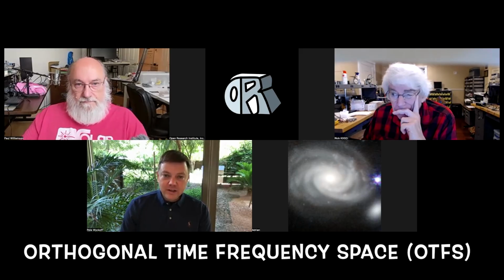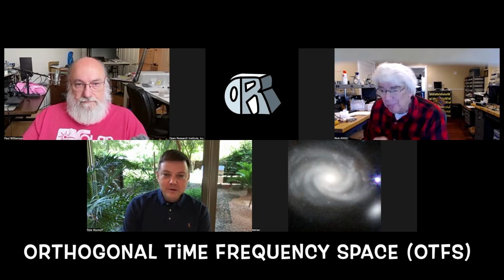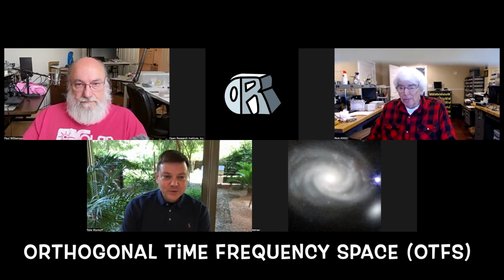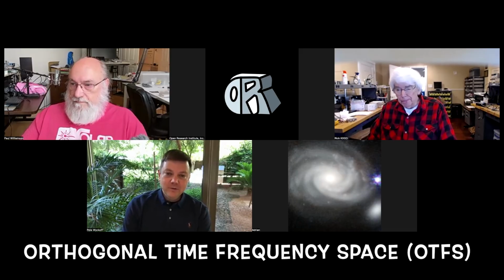OTFS combined for the sort of mission I've been on the last month or so, which is extend OTFS and don't use it the normal way, with an equalizer and so forth to sweep up your multipath. It's to design an OTFS waveform that should focus the energy in time and delay and Doppler, focus in delay and Doppler once it bounces off the moon. So I think in all likelihood, the first FSK waveform for Eve is low technical risk. The conventional OTFS waveform for moon bounce is low risk, and we'll see how it works. Is it better or worse than other things we're already doing?